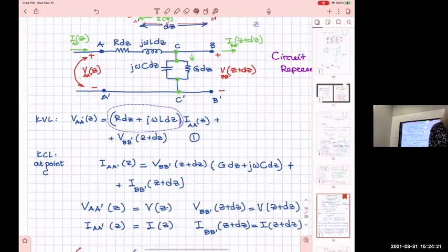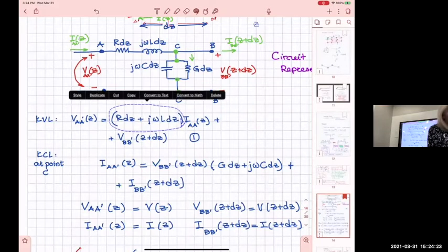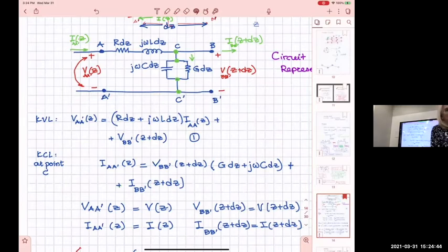And this voltage drop is this sum times the current that flows through, all right? So j omega L is like another resistor, but it's an imaginary number. We are in the phasor domain. You remember, you've done that. So you always treat R and L like this in the phasor domain.